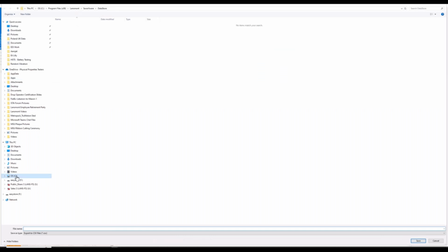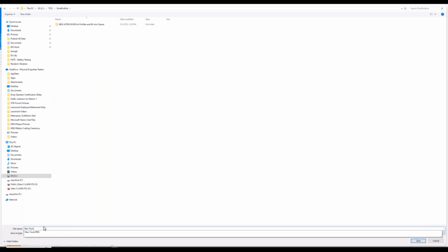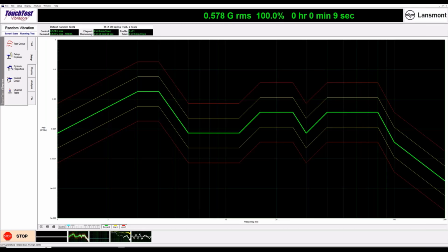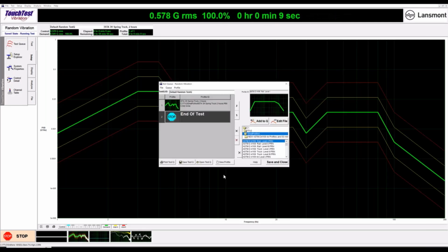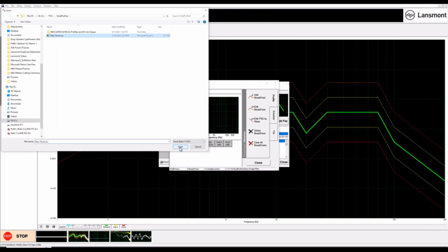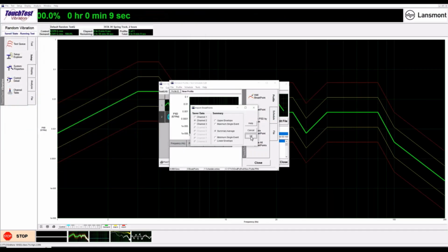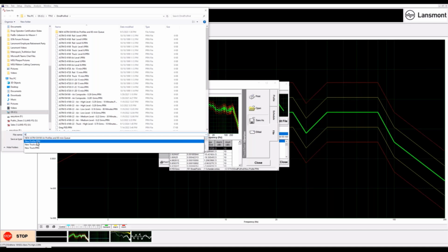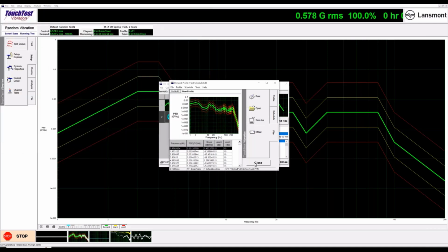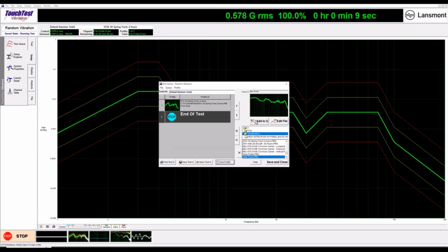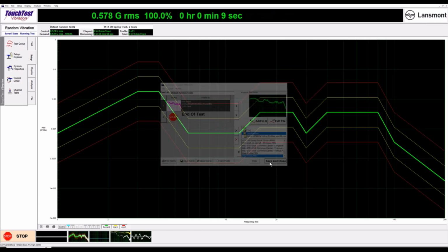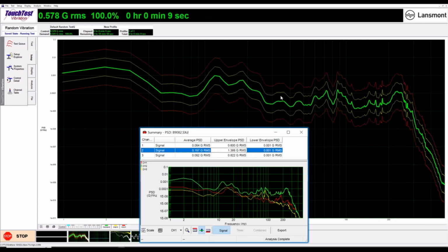And when I generate that summary PSD, I'm able to export that summary PSD from the software. I export that, and then I go to my vibration controller, and I'm able to import that very same data that I just exported. I pick the appropriate channel that represents the vertical vibration, and I create a test PSD. It's as simple as that. It's kind of like, for us, the poster child of our little field to lab process, but it works, right? I'm able to generate those summations from field data, create PSDs, and then import those.